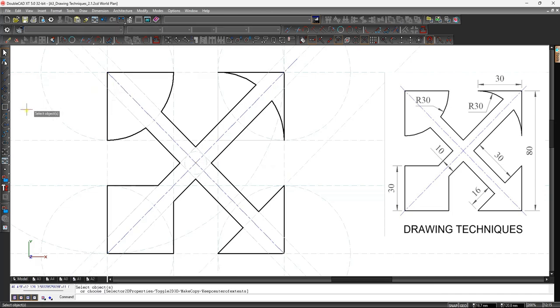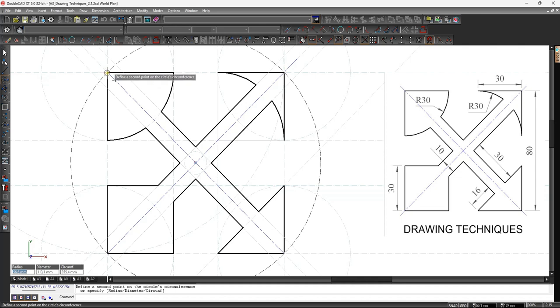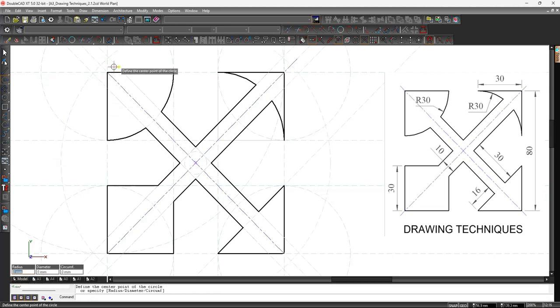So what I'm going to do is select the circle construction tool, and from the center I'm going to just measure what's the distance there. It says 56.6. So if I were to add, let's say 5 millimeters, any distance that you want to, I'm going to say, let's say 61, and enter. That now gives me a reference point of equal distance to each one of my center lines.